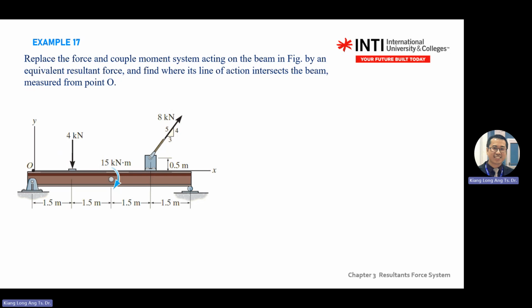Once you have the diagram ready, you need to do two main things. You need to handle the force equation and you need to handle the moment equation. There are two main steps there. For the forces, you find the resultant of the forces in X, in Y, then find the final resultant with the angle, transfer to O. Then after that, you do moment.